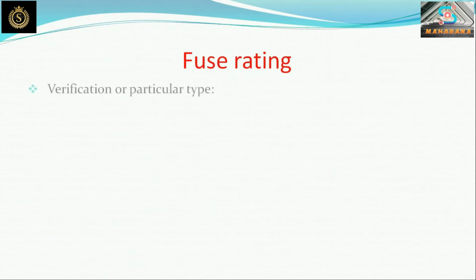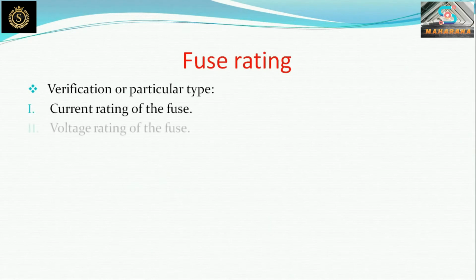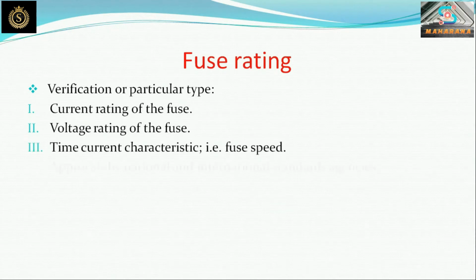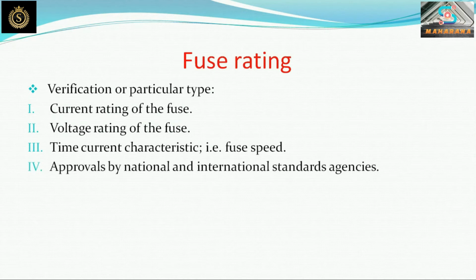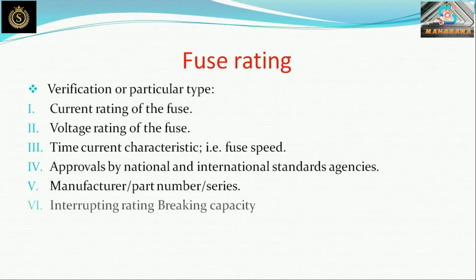Fuse rating. Verification of a particular type. 1. Current rating of the fuse. 2. Voltage rating of the fuse. 3. Time-current characteristic, i.e. fuse speed. 4. Approvals by national and international standards agencies. 5. Manufacturer/part number/series. 6. Interrupting rating, breaking capacity.